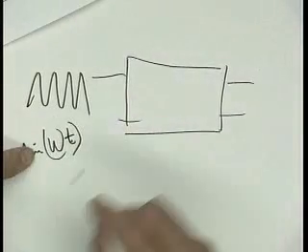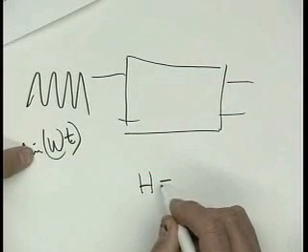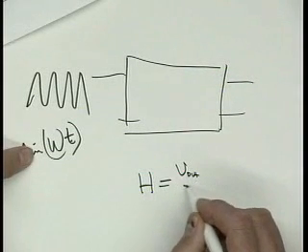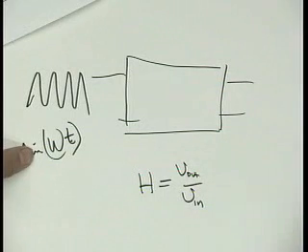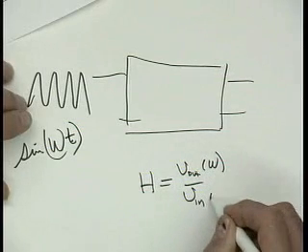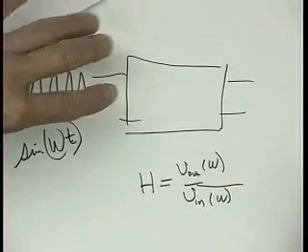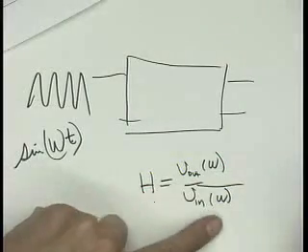And what we will now do is figure out transfer functions, whereas before we had V out over V in, not as a function of frequency, only at omega equals 0, we will now calculate it as a function of omega, or frequency. So what happens to our circuit as we change the frequency?